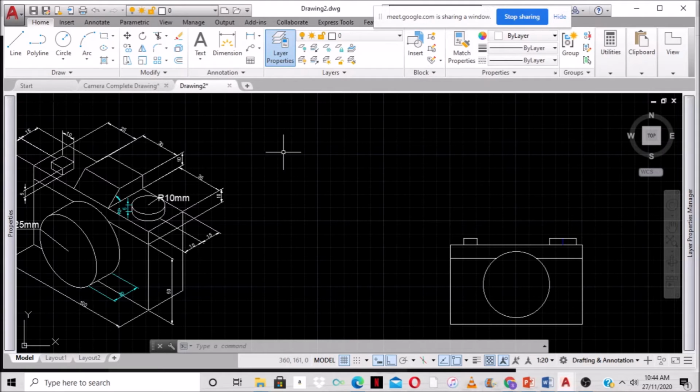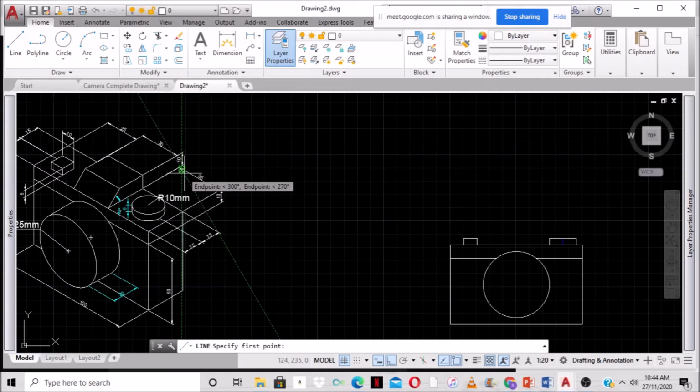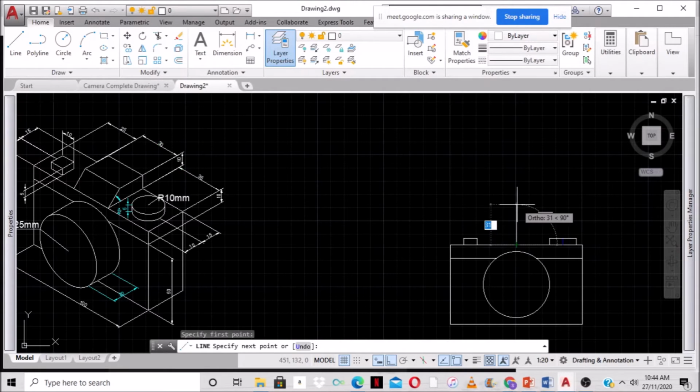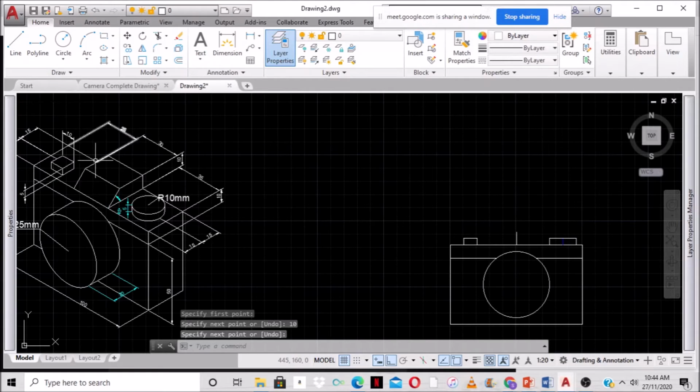So all we're going to do now, we are going to select a line command. So remember now, the flash would have been in the center. You know why we say that it's in the center? Because remember from here to here is 35, right? And this is 30. So if we should go off of this, it would have been 50, right? So if we come to the center, it's 50, right? And we go up by 10. Because remember the flash is 10, right? Spacebar to get rid of the command. So now what we can do now is that we can just go 15 on either side. You following? To get the 30. Yes, sir.